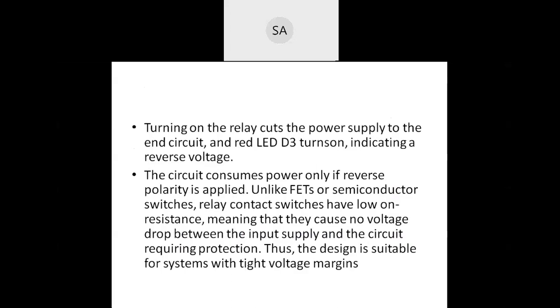This reverse voltage protection circuit prevents damage to power supplies and electronic circuits in the event of reverse voltage applied at the input or output terminals. To block the negative voltage, designers usually place a power diode in series with the power supply. It is the simplest circuit. Under normal conditions, the diode is forward biased. Under reverse battery conditions, the diode is reverse biased and no current flows, which protects the load. Here we are connecting the diode in series with the battery and load.